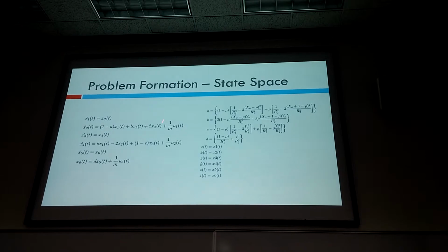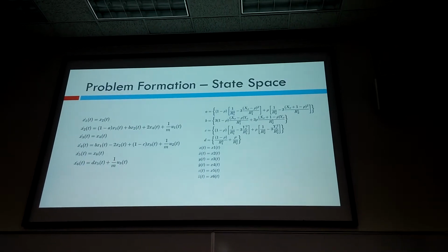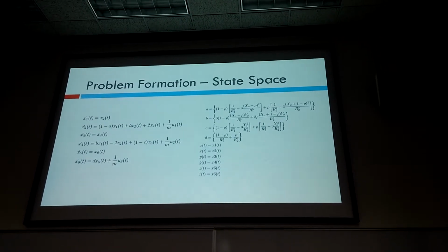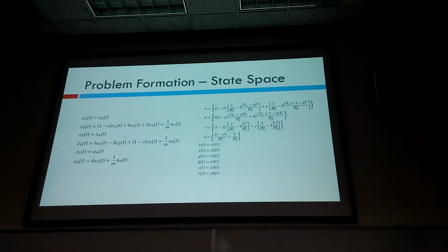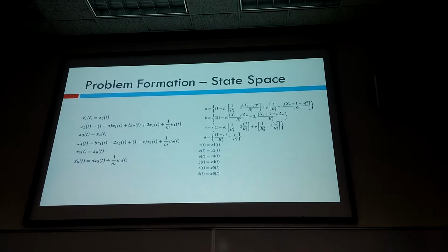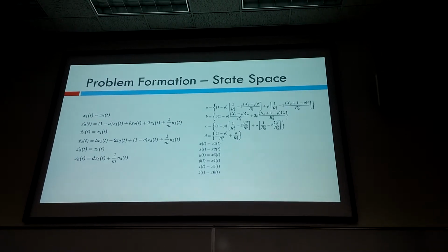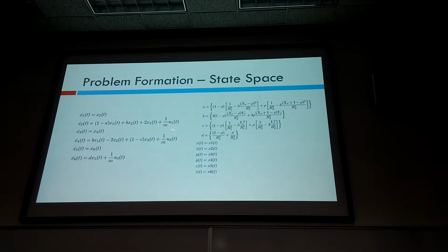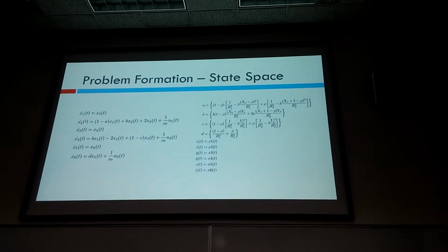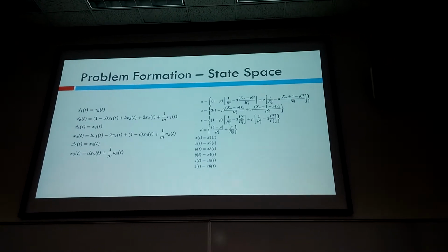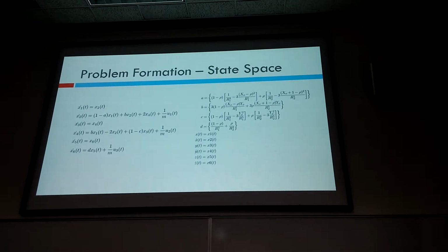Here we've also included our control signals, U1, U2, and U3. For the satellite, we're assuming that a thruster is positioned on all 6 sides of the satellite, so it will be able to control the satellite's motion in the positive and negative x-axis, positive and negative y-axis, and positive and negative z-axis. Also, our control signal here is force. It's the force of the thrusters. So we attach those to the acceleration states, and then we just multiply by 1 over m, because force equals mass times acceleration, and that way all the units stay the same.